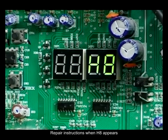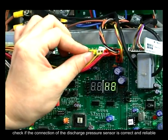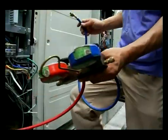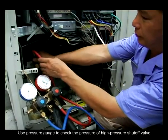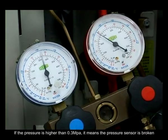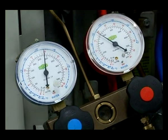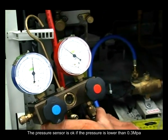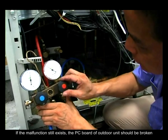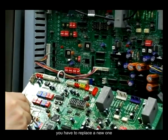Repair instructions when H8 appears. Step 1. Check if the connection of the discharge pressure sensor is correct and reliable. If it is okay, please go to the next step. Step 2. Use pressure gauge to check the pressure of high pressure shutoff valve. If the pressure is higher than 0.3 megapascal, it means the pressure sensor is broken. You have to replace a new one. The pressure sensor is okay if the pressure is lower than 0.3 megapascal. If the malfunction still exists, the PC board of outdoor unit should be broken. You have to replace a new one.